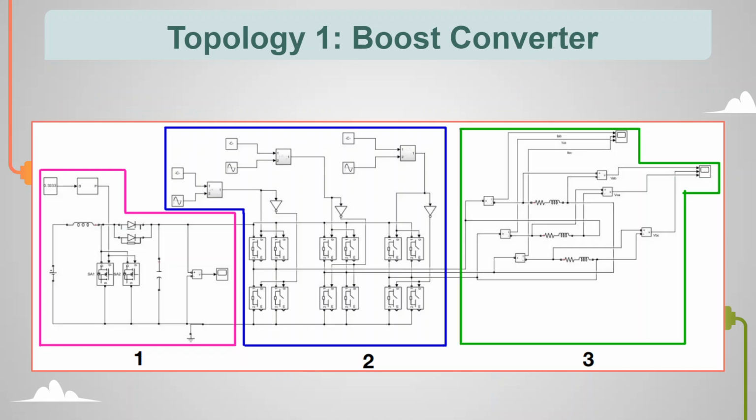Looking at our circuit, the first leg of the diagram is a boost converter. We use the boost converter to take the 400 volt battery and output a stable 600 volt source for our inverter stage. The boost can account for any slowing of the inverter's response time due to any fluctuations in the battery as it may be charging or discharging.